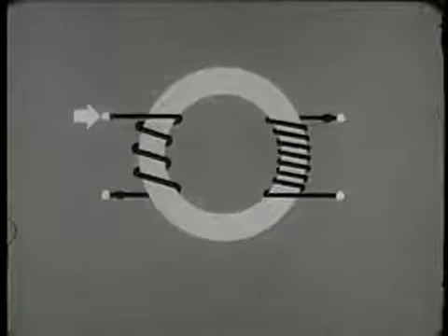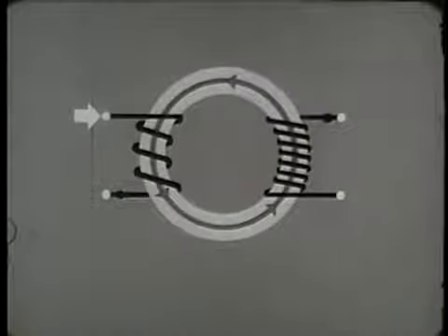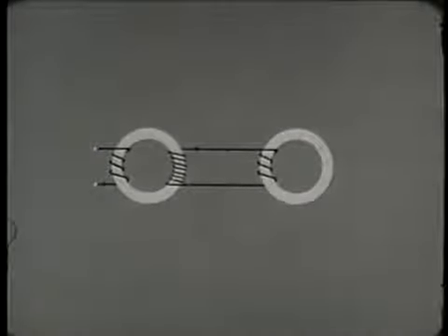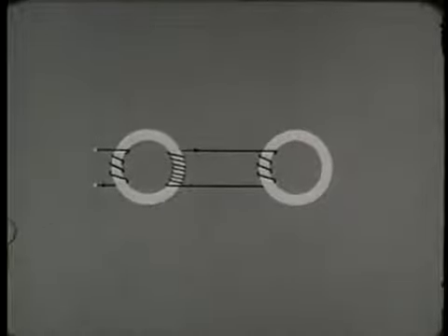Now suppose we want to send non-dot current into the core, setting it to the binary 1 state, but we don't want to send current out, at least not yet. By connecting in a second core on the right, we can see more clearly what the problem is. Now, the first core's output winding is directly connected to the input of the second core. This input has been wound so its polarity is the same as that of the input of the first core. The dot side is below.